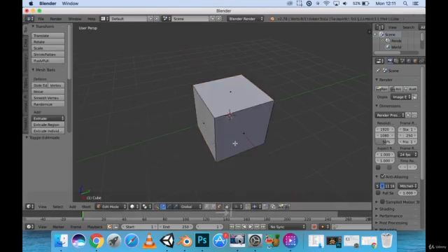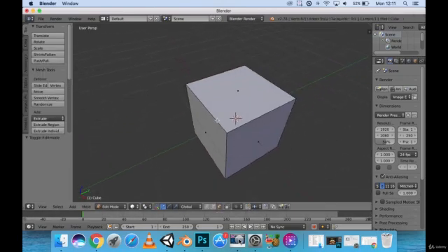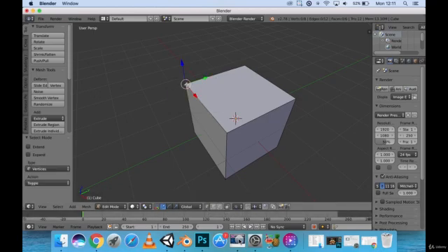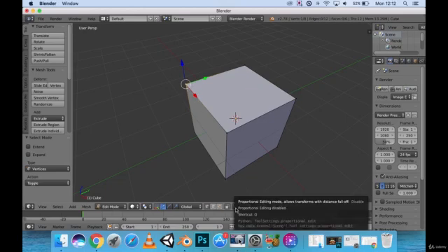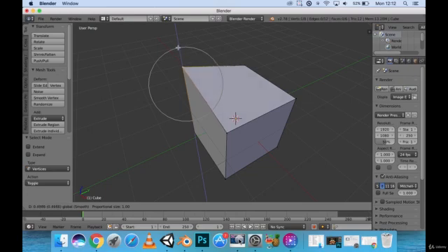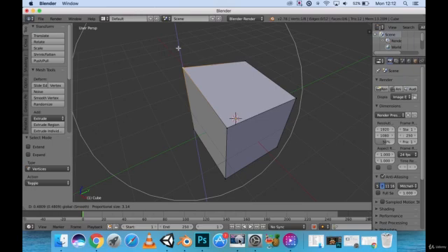We're going to go back into edit mode. Another of the tool options or controls that I'll be using quite a lot. I'm going to click Control Tab. Let's go into vertex mode. Let's select, let's say, this vertex right here. I'm going to turn on the proportional editing mode, or you can just simply click O, and that should turn it on. We can move this single point right here, or we can scroll up our selection area.